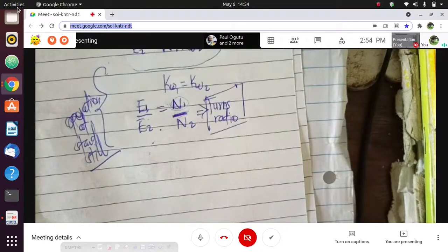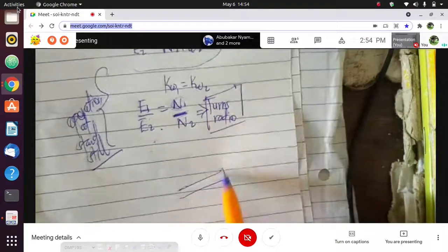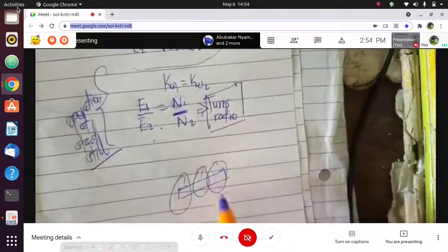Remember, we induce voltage in the stator. This induced voltage induces a voltage in the rotor. If that rotor circuit is closed, then a current is produced. And what happens when you have a current-carrying conductor in a magnetic field? That conductor will have a magnetic field around it.